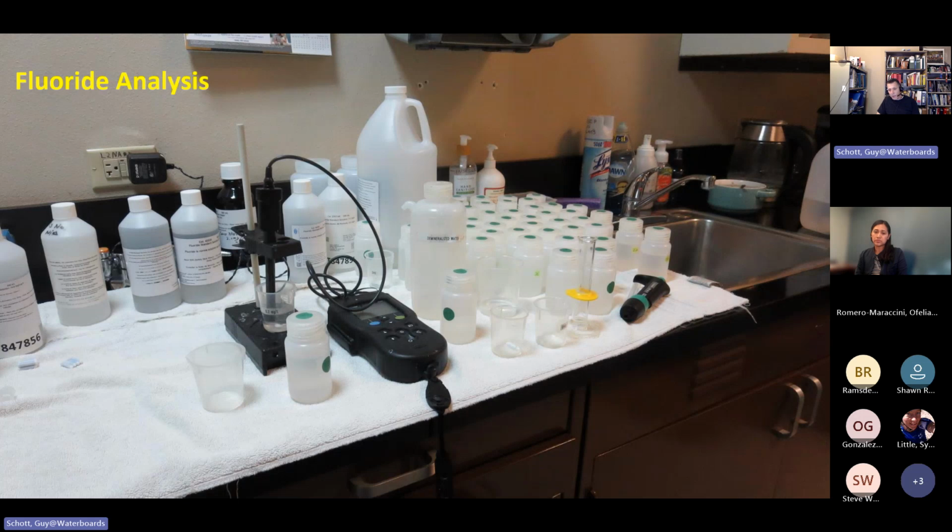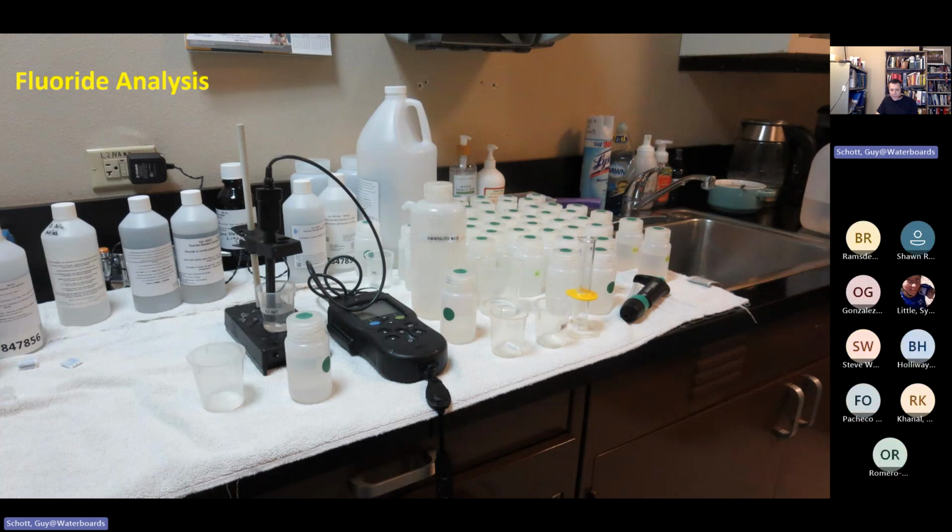But I think, Sean, if you're going to go to the hydrant, the sample tap, the faucet in the pump room will work. I would suggest you have a 5-gallon bucket inside the pump house so you don't get water all over the place. You can turn on the faucet, let it go in the bucket, and then take your sample and then turn the water off. And then on the inlet, you just keep that running the whole time. Okay. Yeah.